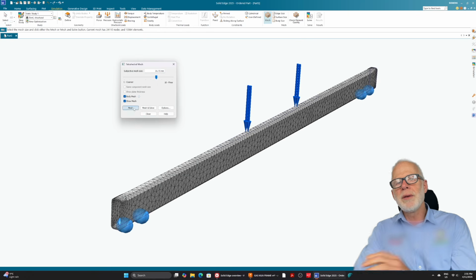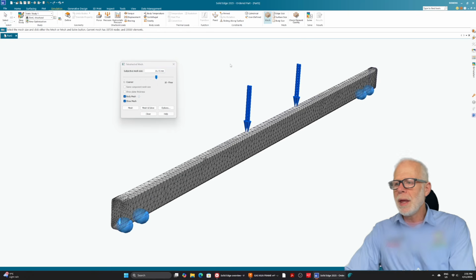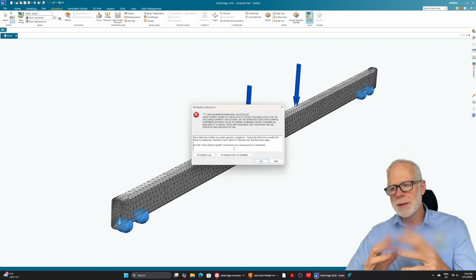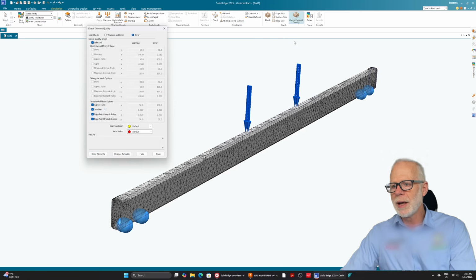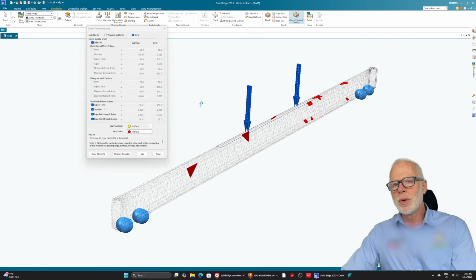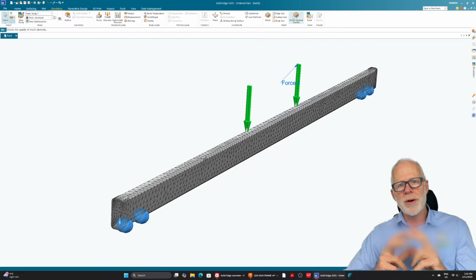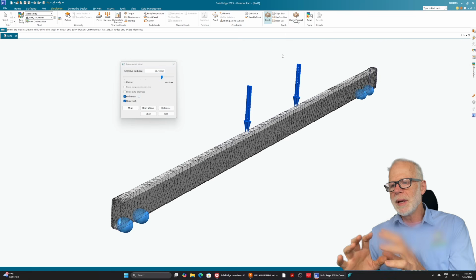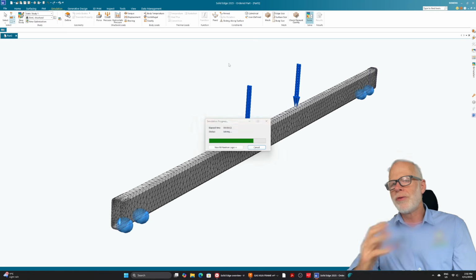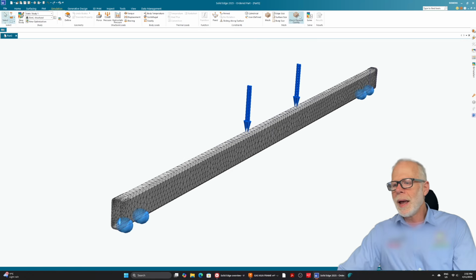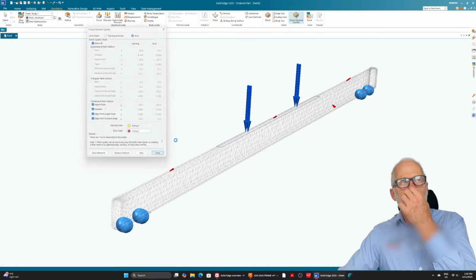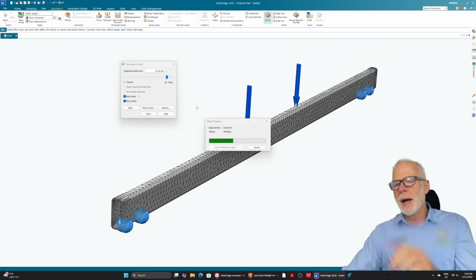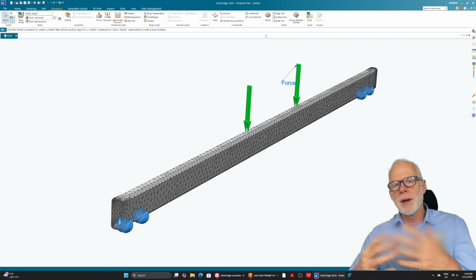I was going to give up completely on the 3rd failure, but I was thinking I should go coarser to try and resolve that issue. But when I asked Google Gemini, I got my phone, got Gemini up on my phone, and asked it to read the error message, and it advised me to go finer, not coarser, and that improved the result. And when you see these red elements in the testing step, that indicates that there's less problems and you're going in the right direction.